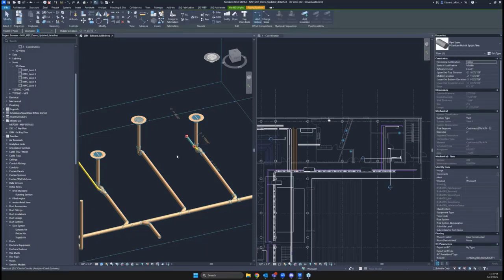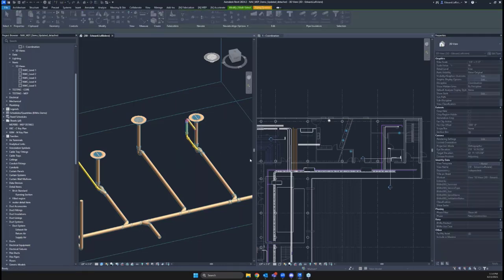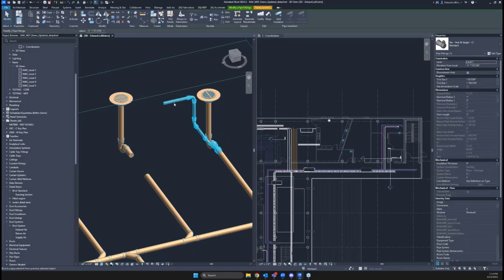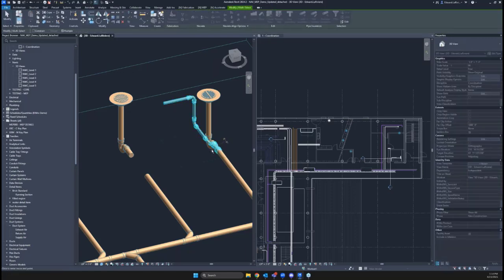I'm going to throw an elbow up, then an elbow over. If I miss the direction, no worries. We'll rotate fitting to turn that back the correct way. I'm going to use my version of split with gap, which cuts a hole without placing couplings. I'm going to tab select that element set I'd like to continue using and move it over here.